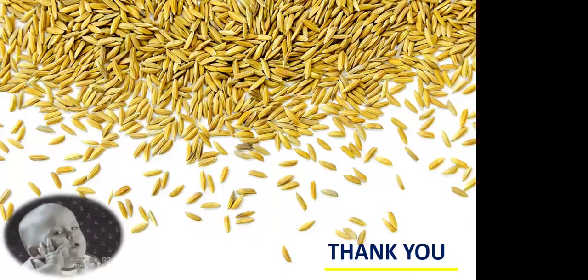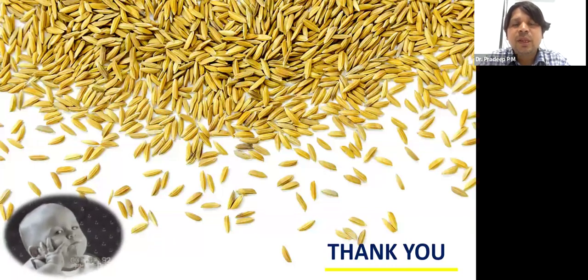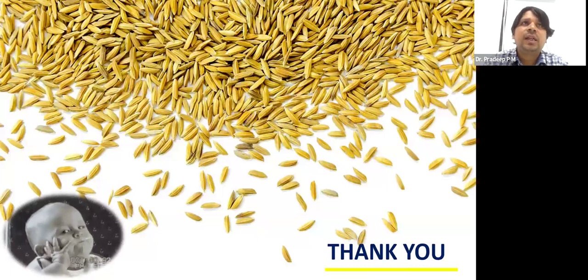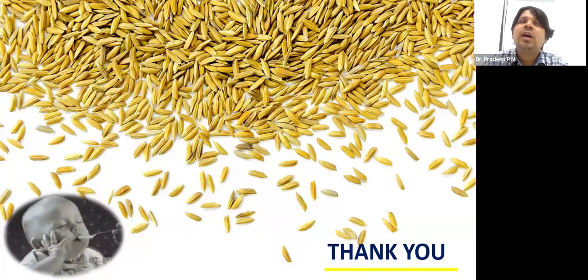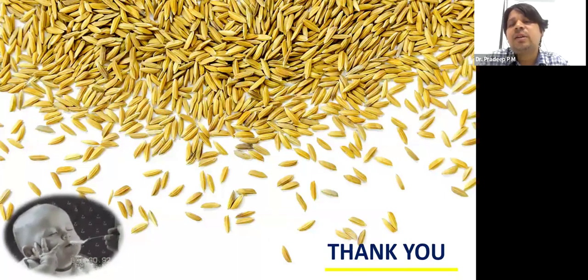Okay. And what is the purpose of cleaning paddy after drying? Yes, as I told, nowadays we have a lot of automation which is built in the system. Automation means we rely on sensors. So there are so many sensors which are there in the machine system. So what happens if the paddy is not clean? Think that there are stones or stakes or plastic items, metal pieces. So this will damage the sensors and the internal parts of the machines or the systems. So this will impede the productivity. So to overcome that, we have the cleaning systems installed at regular intervals.